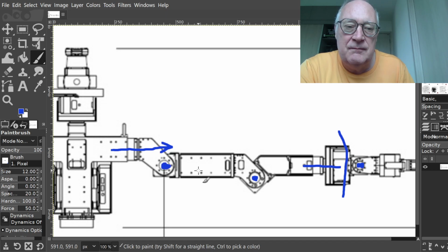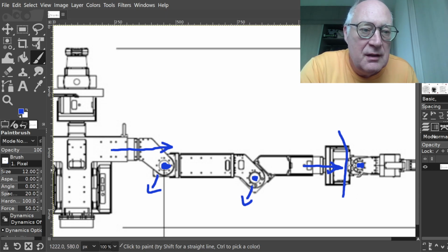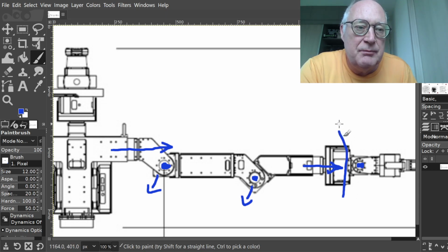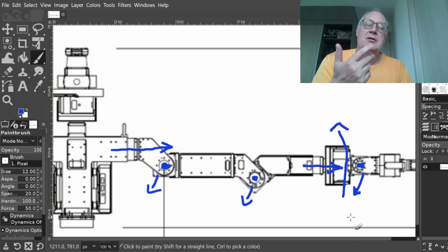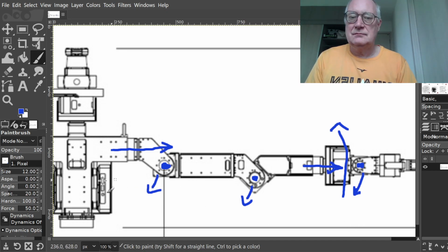Now those two here, the horn is in our direction, so I want them to point out of the page. Like in 3D, it would look like this a little bit. Here is the servo horn this way, so I want Z-axis to be located that way. Here, the horn is on the top, so Z-axis should be rotated this way, and here it's also mounted that way, so it should be pointing out of the page. So these are the Z-axis for our joints.